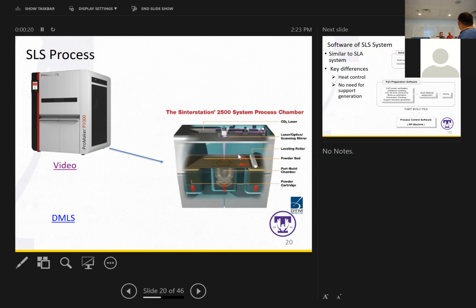Yeah. Because it's a solid powder, as long as the powder is strong enough to push away, you don't put the energy over. But I have a hatred for SLS. People don't pay attention to material properties of powder. Some of it's toxic, some of it's explosive, some of it's fire. People have caught a lot of those machines on fire. Yeah, so on the leading edge, on the bleeding edge.